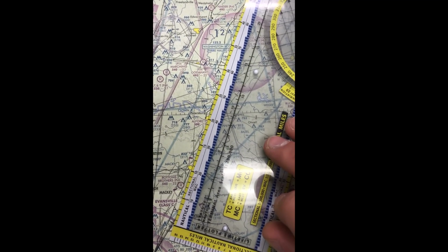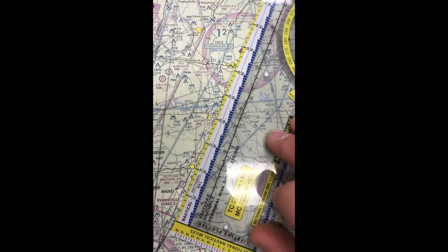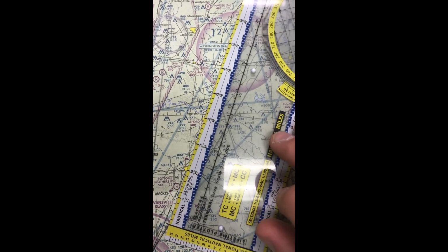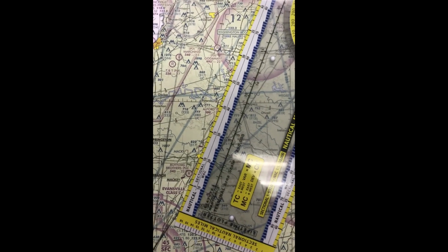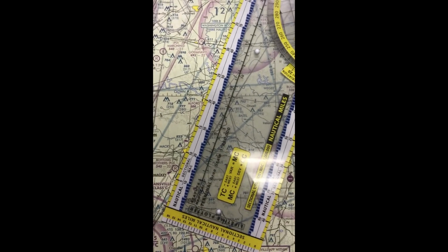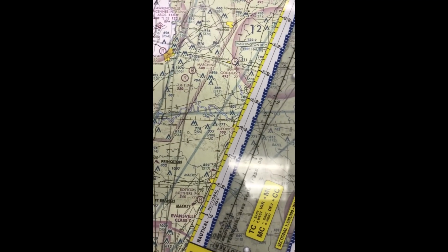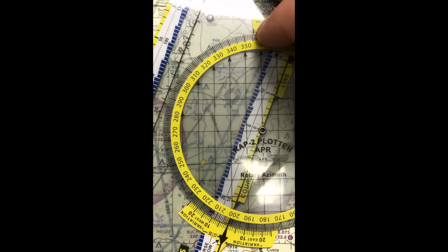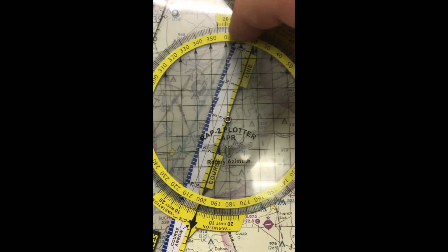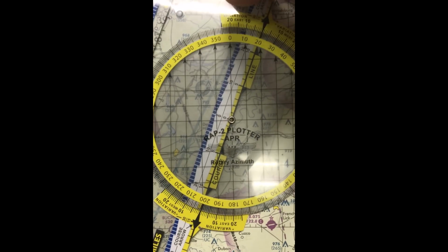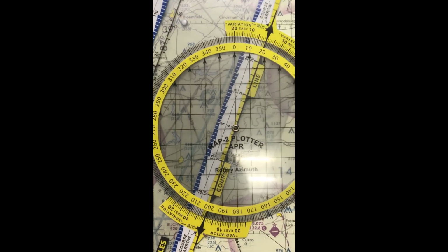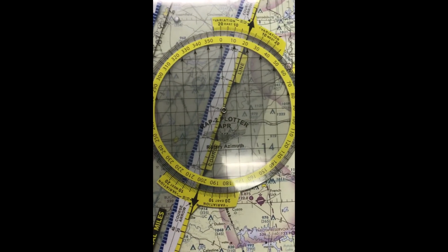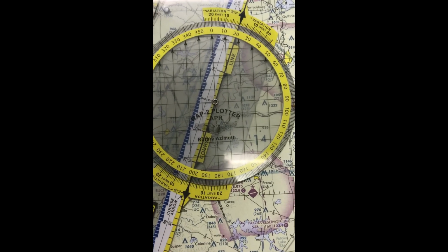I'm sorry, that's going to be Petersburg, near that Alfred Private Airport, and we'll use that for our next navigation leg. We can see that is going to be 20 nautical miles, so we'll jot that down, and then we'll go ahead and come up with a true course for that one. Again, keeping it all lined up with a straight edge, we spin it in with our plotter, get it relatively lined up with a line of latitude or longitude, and we can see our true course. That's going to get us from top of climb to that first navigation waypoint approximately 020 true.